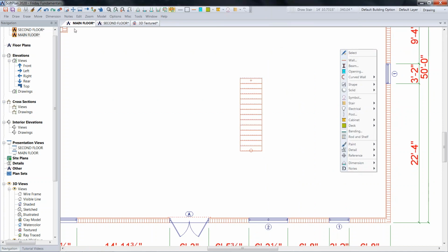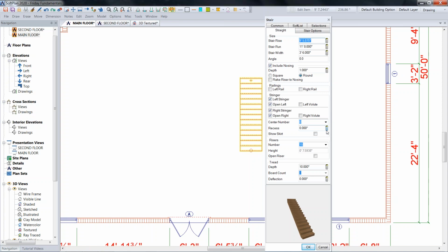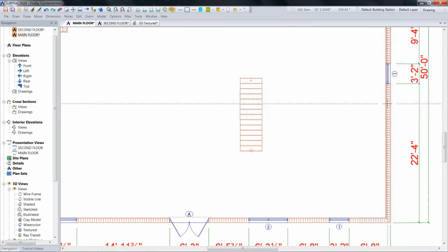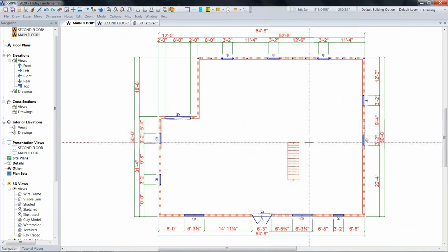There. All right, so let's edit those stairs. And those stairs now have gone up 9 foot 5 7/8 inches. Well, if those walls on the outside are 8 feet, actually they're 8 feet 1 1/8, and I've got 16 inches of joist and 3/4 inch of subfloor, those stairs automatically figured out how they're supposed to grow up. They got it. They figured it out. It's done.